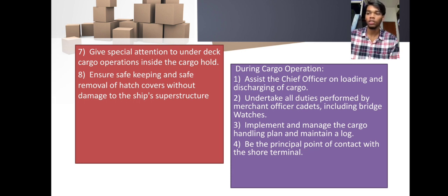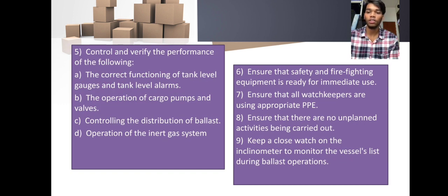And so during the cargo operations, assist the chief officer in loading and discharging of cargoes, undertake all duties performed by the cadets, including bridge watchers. Implement the cargo handling plan and maintain a log. Be the principal point of contact with the shore terminal and control and verify the performance of the following: the correct functioning of tank level devices and tank level alarms, the operations of cargo pumps and valves, controlling the distribution of ballast,